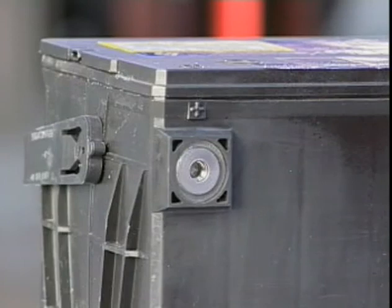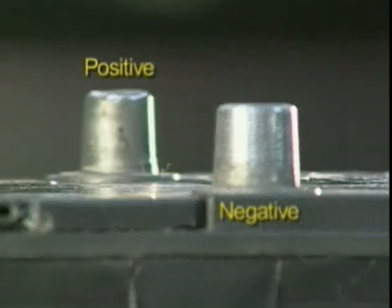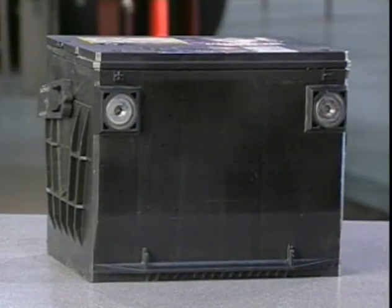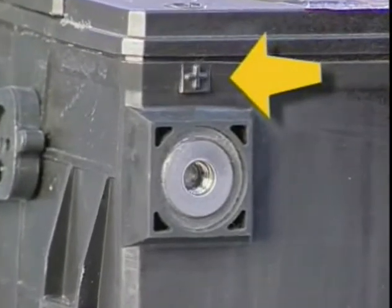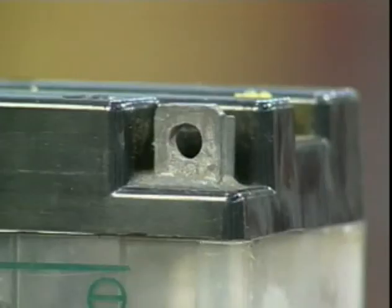Post or top-mounted terminals are commonly used on automotive batteries. The positive post will be larger than the negative post to prevent connecting the battery in reverse polarity. If the battery has side terminals, they are positioned in the side of the container, near the top. These terminals are threaded and require a special bolt to connect the cables. Polarity identification is by positive and negative symbols. Some specialty batteries, and those used in some imported vehicles, may use an L-shaped top-mounted terminal.